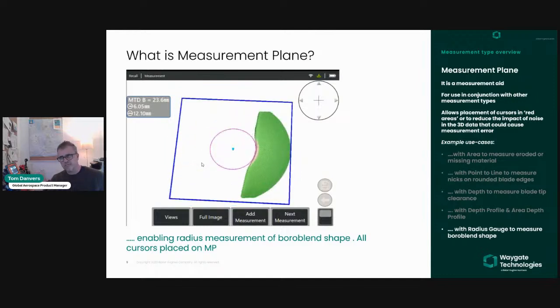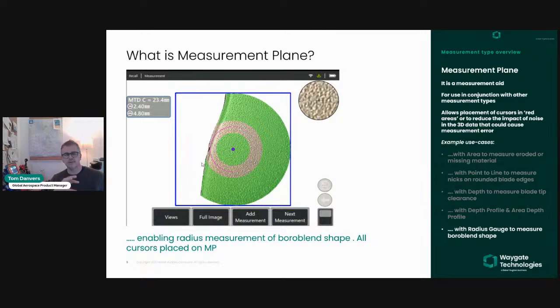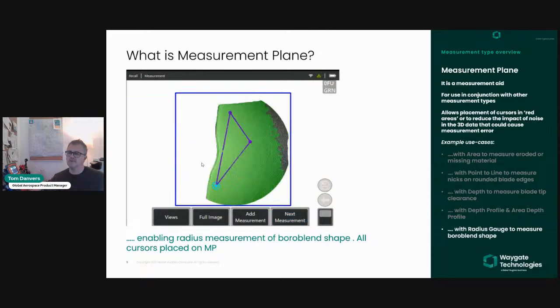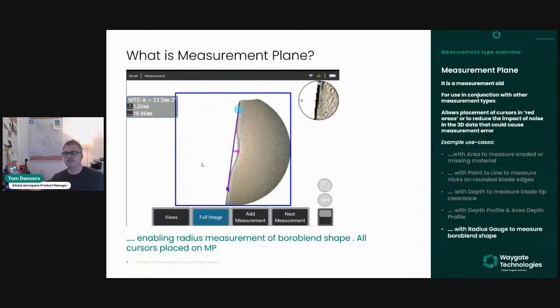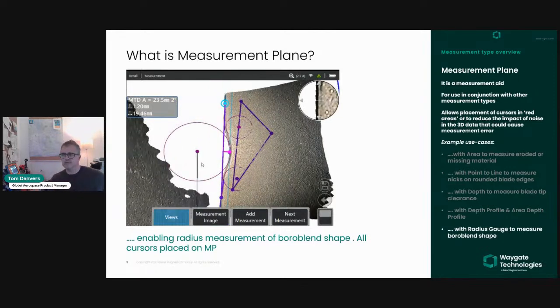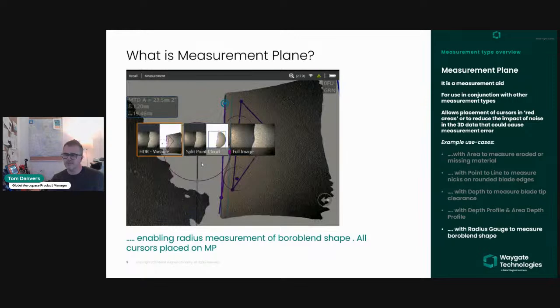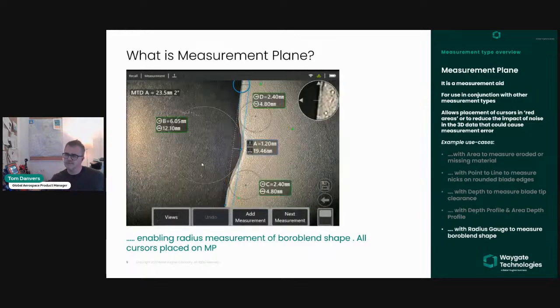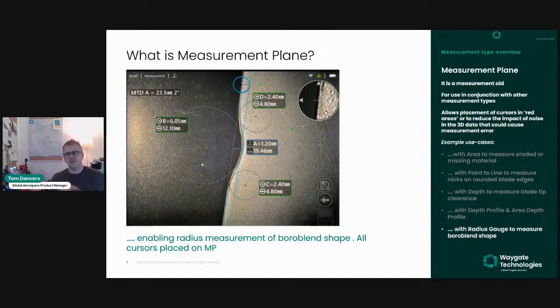The other two smaller circles are projected onto the blade. So there was no requirement to use measurement plane when assigning those other two smaller circles to determine the appropriate shape of that blend lead out surfaces. So if those two were only needed, then you wouldn't need measurement plane. But that third circle that you see on the left-hand side, yes, in order to be able to make that shape happen and determine that value, then you do need to assign a measurement plane to that image.